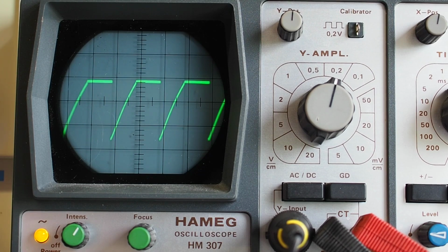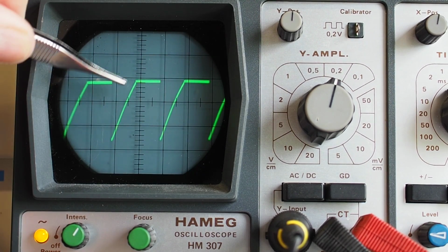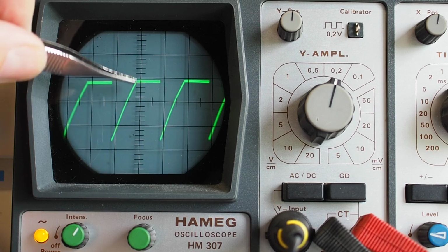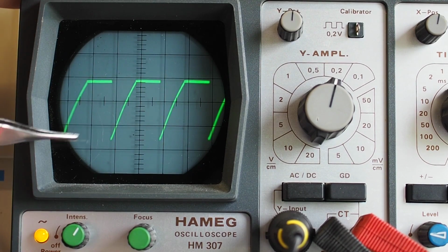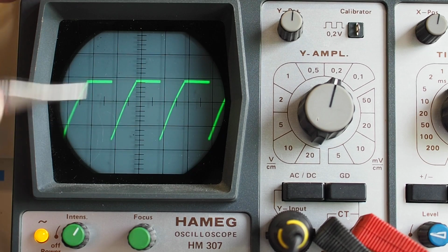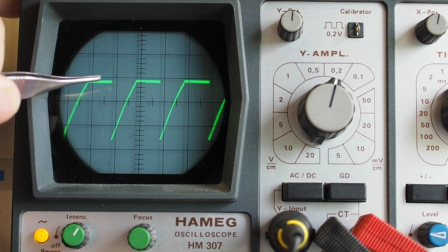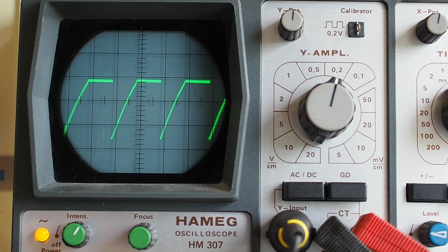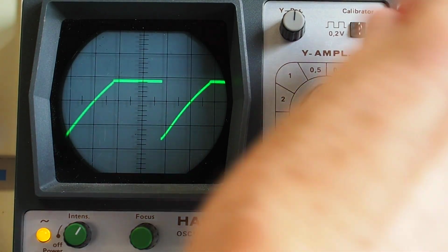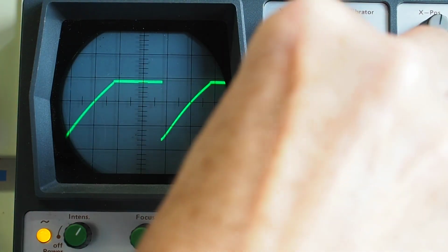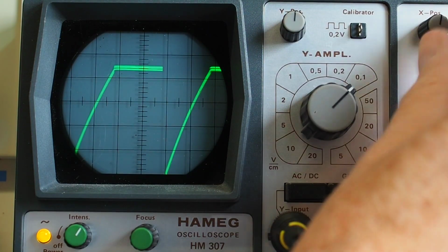First of all, what we're actually seeing is the charging curve of the capacitor there on that rising edge. And if you look closely, I appreciate that's not terribly easy to do, in fact, if I just change the time base, we might actually be able to achieve that. Yeah, there we go. I'll just make that a little bit higher there. Yeah, okay.